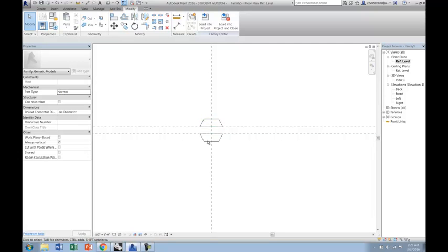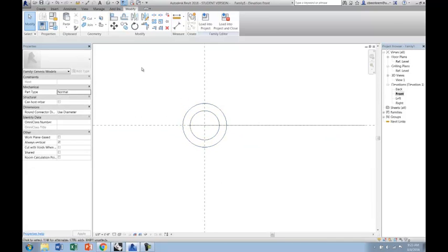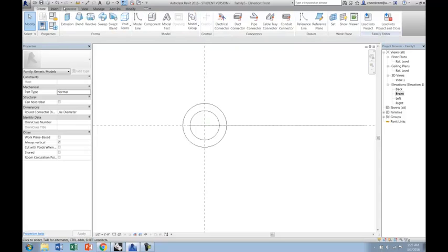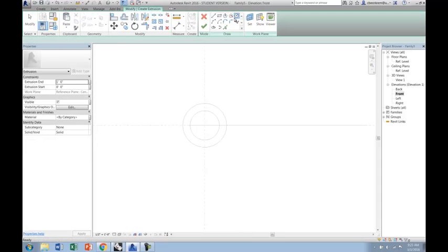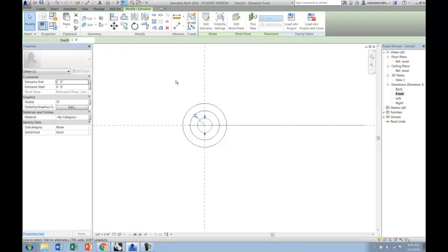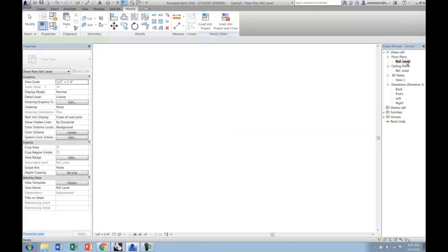I'm going to add in the screw, basically the threaded rod that'll move between these 2. So we need to look in the front elevation here, and I'll go to create, extrusion, and draw another circle at the center point. And this one we'll just do, say, with a 1/4 inch radius. And I'll leave the extrusion at 1 foot right now, just so we can see it in the reference level.